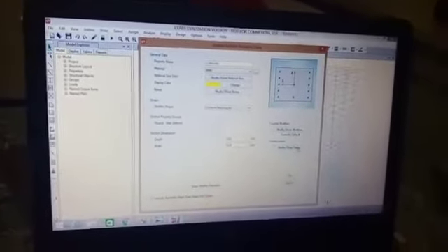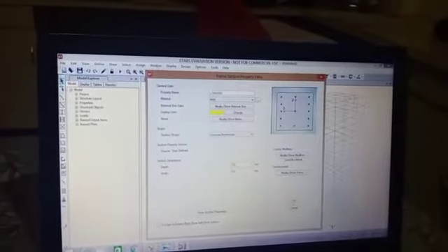And now choose modify show rebar to see the reinforcement, and change the longitudinal bar as HYSD 415 and confinement bars as mild 250, and make sure that the clear cover is 40 mm. And now click on OK and OK again.